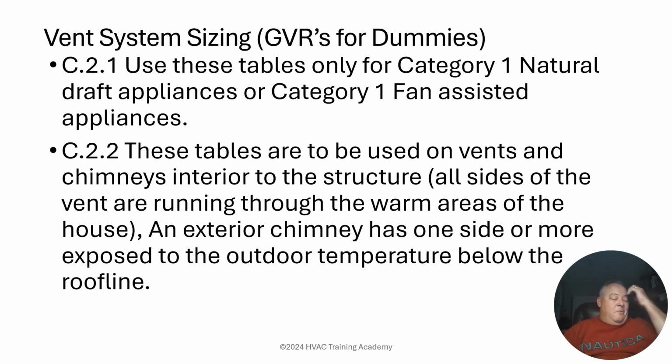Now, again, it's very rare that you're going to get into these situations. The last time I dropped a liner, I'm trying to think of how many years ago it was. Because now we're looking at Category 4 appliances mainly installed here in Canada in a lot of our applications. So we could be pulling out an old furnace, but typically we're not using that chimney to revent anything. We could have it still remaining for a natural draft Category 1 water heater, at which point we'd have to drop a liner. But again, it's becoming rarer and rarer that we're going to be performing this.